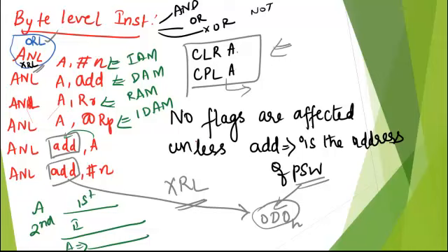Also here, the address is part of the instruction, maybe the destination is an address and the source is immediate data. We can say immediate addressing mode, and mostly it will be called immediate addressing mode. You can even consider the address, though it is not the address of the data, it is simply the destination address. So you may even call this direct addressing mode.